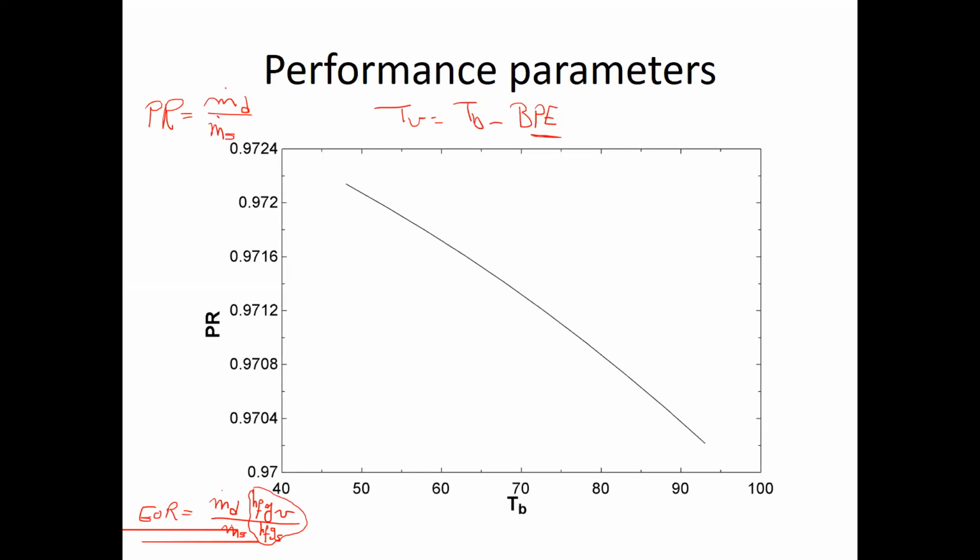So they are related. Remember that when we did the balance, we said basically that the source of heat coming to the unit, where the evaporation is occurring at a certain temperature, is the latent heat issue which is controlling the parameters here.